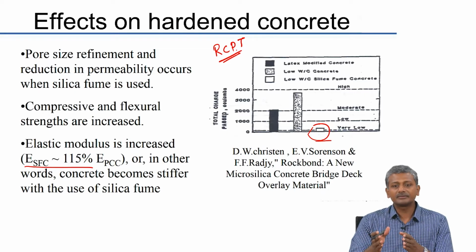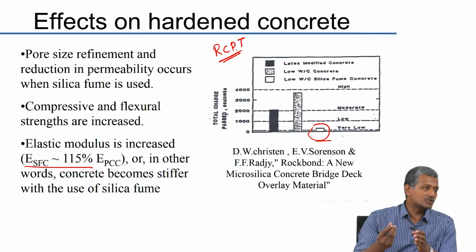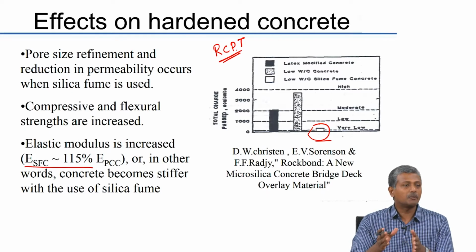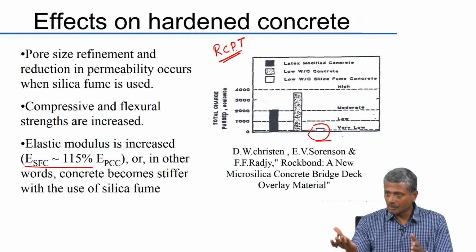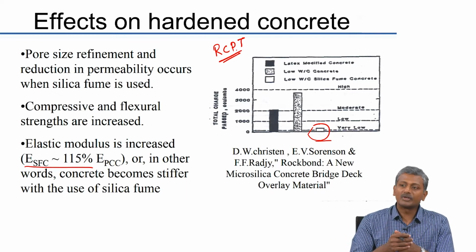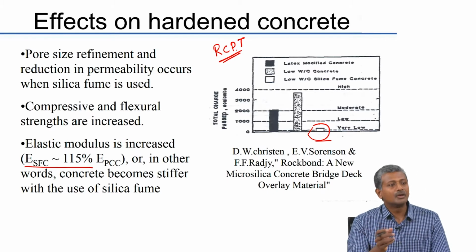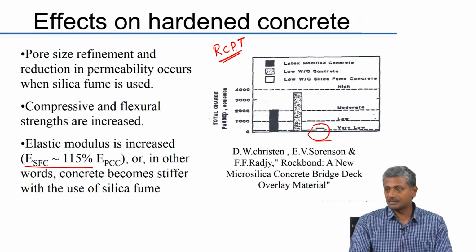Now the problem here is when you have concrete which is saturated, you know that there are ions in the pore solution of the concrete. We talked about the fact that there are sodium, potassium and hydroxyl ions. When you apply a potential, obviously those ionic species also start moving around, right. The charge carrying ability of the concrete will depend on the amount of ions present in your pore solution. So when you introduce a finely graded silica in the system, amorphous silica, these ionic species, sodium, potassium and hydroxyl ions, get trapped inside the silica glass, because of which charge simply cannot flow through these systems.